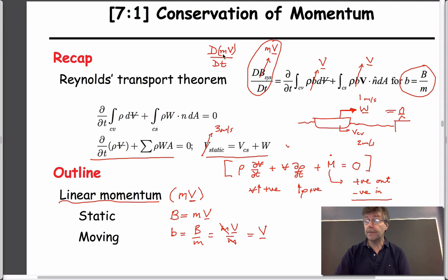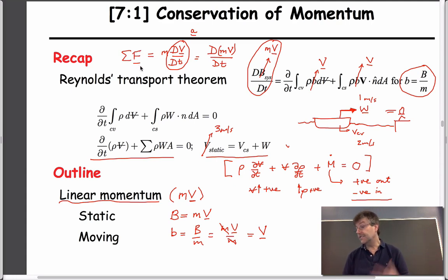And if you look at this and think about what it is, if we write it a slightly different way, I guess if we wrote it as mass times, if we thought that the mass wasn't going to change, then this might look something slightly more familiar to you, right? This, by definition, is acceleration. And so this, actually, by definition, is sum of forces. And so that's actually everything we need to do for Reynolds transport theorem to get it to work for conservation of momentum.